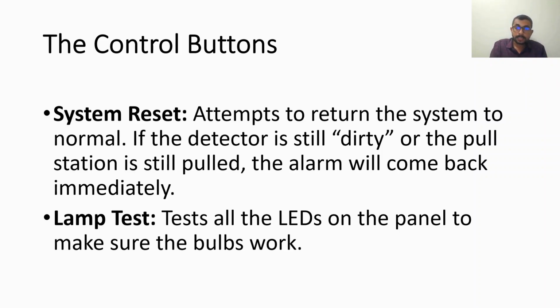Then we have the lamp test button. The lamp test button is to ensure that all the LEDs on the panel are working properly. When you press the lamp test, all the LEDs will start working in a sequential manner, which is the standard for all the brands. So you have four buttons: the acknowledge button, the silence button, the reset button, and the lamp test button.